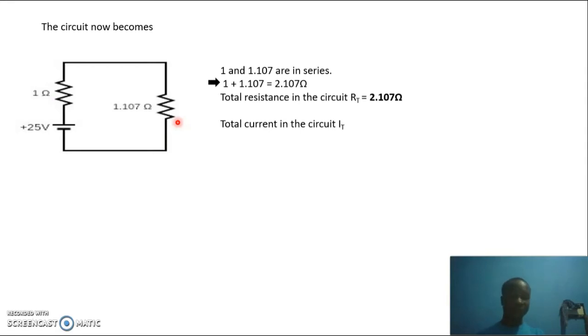So using that formula by Ohm, we can do some change of subject there to make the current our value that we are looking for. So we do simple change of subject, making current the subject, so we get current which is equal to the voltage from the source divided by the total resistance.